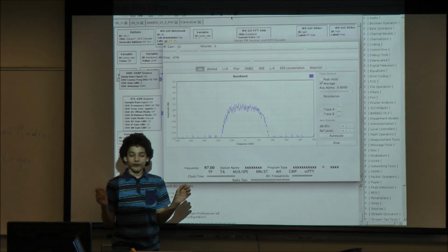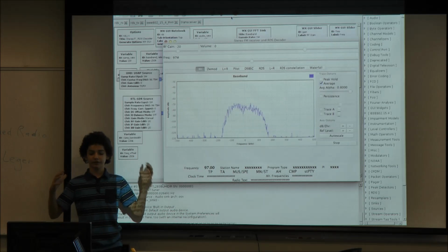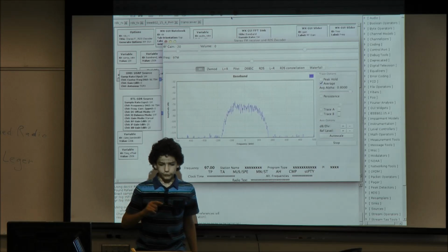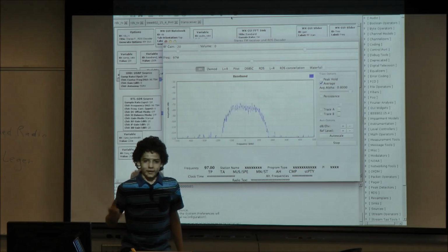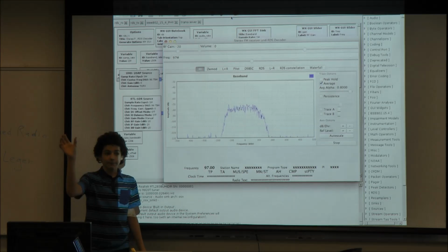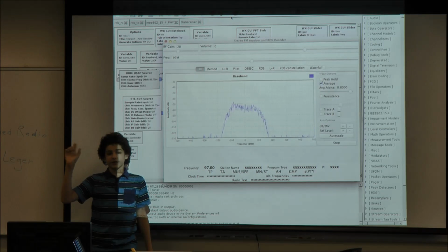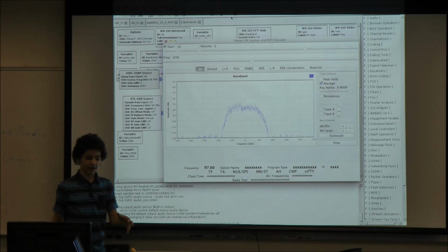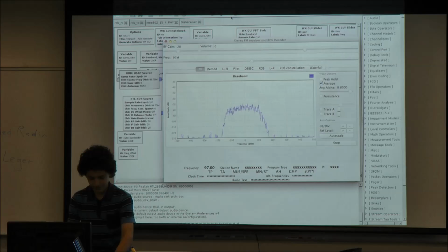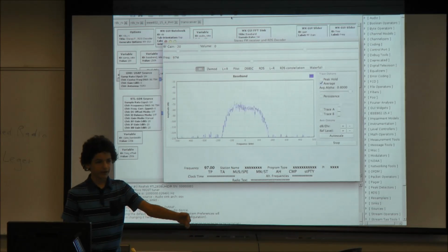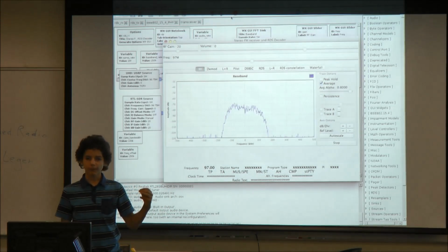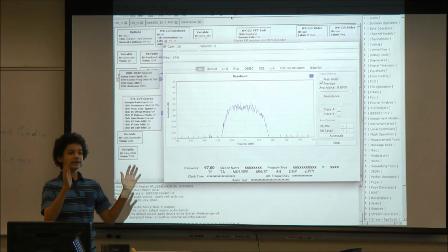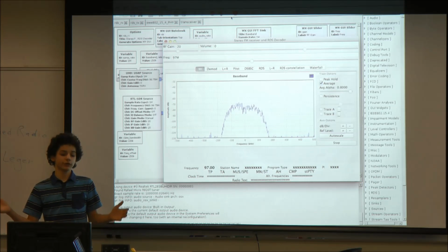One of the important things to know with software-defined radio is that you have a lot of data. This dongle here is doing about 1 megasample per second. Each sample is 2 8-bit values, so it's doing 16 million bits per second. And then your computer needs to be able to process it. Your USB interface also needs to handle it: if you have 20 of these plugged into the same USB controller, it probably won't work well, because each of them is essentially saying, through a hub, I need to send data, and I need to send data, and eventually there's no more room.